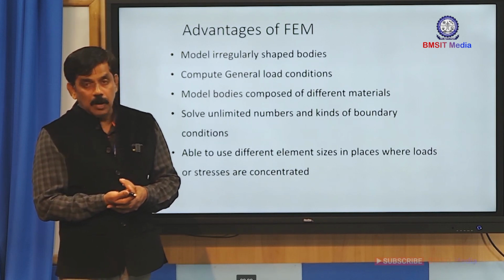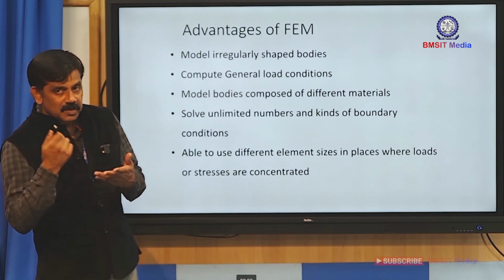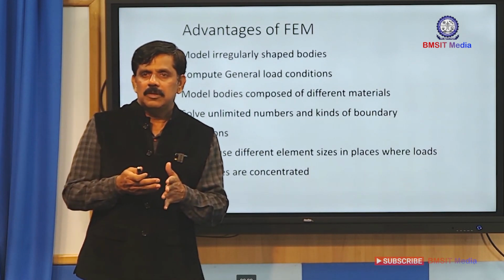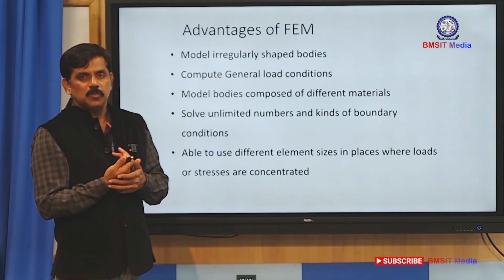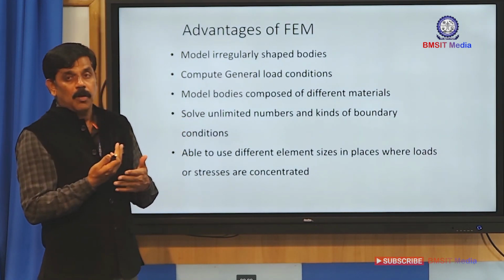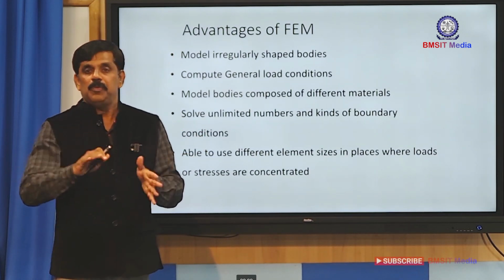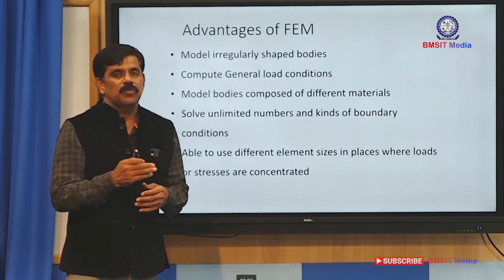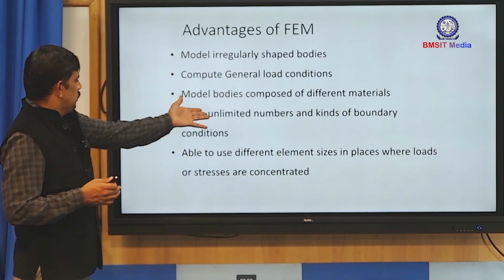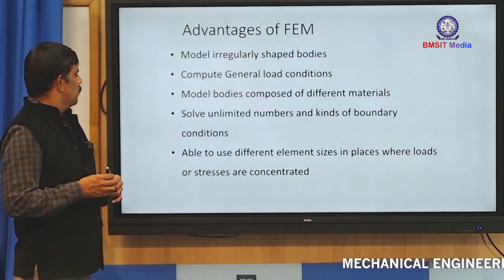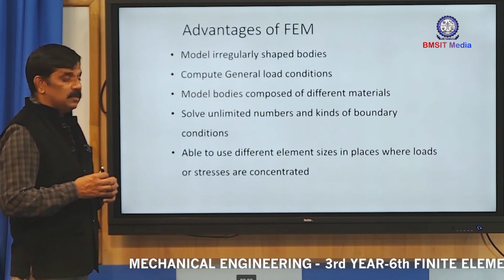Loading conditions may be very complex. In the normal case, it may be a simply supported beam, or a fixed beam, or one end of the bar may be fixed, but here the whole surface of the component may be fixed. Then the boundary conditions are more complex. The loading conditions are more complex. The loading may be non-uniform, or it may not be uniformly varying also. In such cases, we have to go for finite element analysis, which has more advantages. And as already shown, you can go for unlimited boundary conditions, and for element size, we can go for finer meshes.